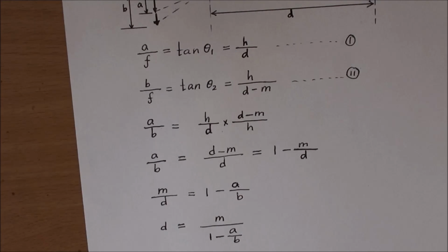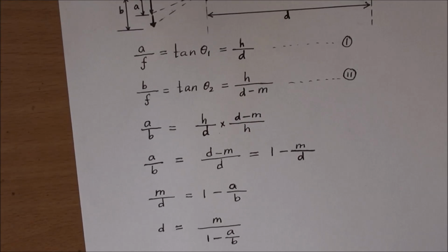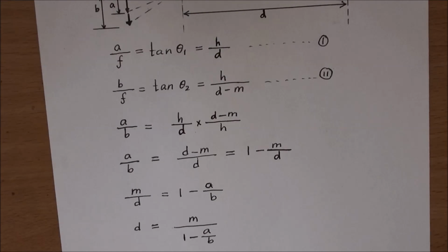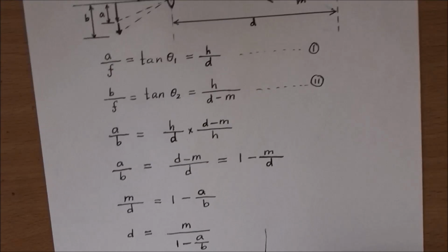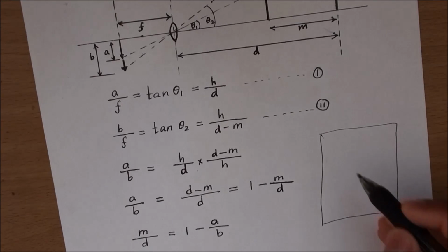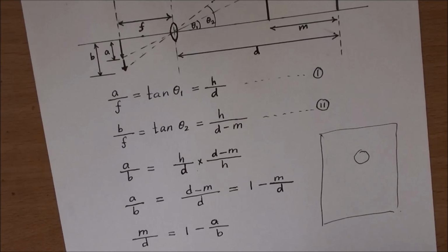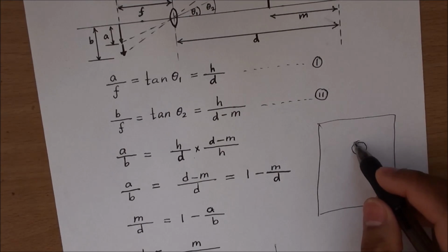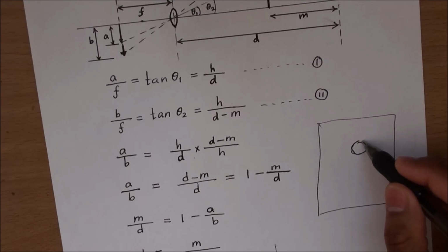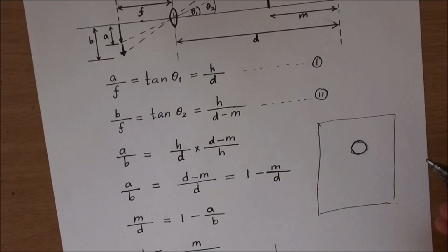But of course, to be able to figure out the height of an object or the size of an object, you need to count the pixel distance, and this is where the edge tracking comes in handy. So you need to have some algorithm to find out the edges of an object. So if this was your camera view and you had an object on the first snap, you need to be able to figure out, in this case, the perimeter length. So notice how this applies to length, not area.